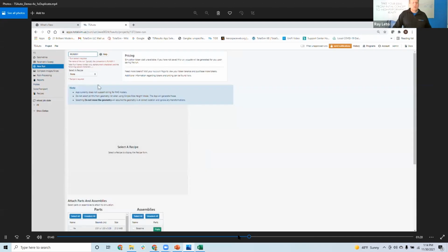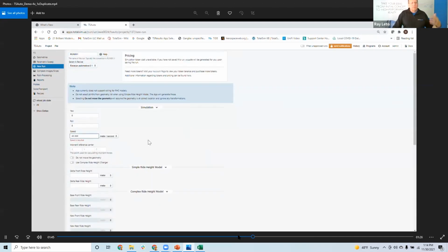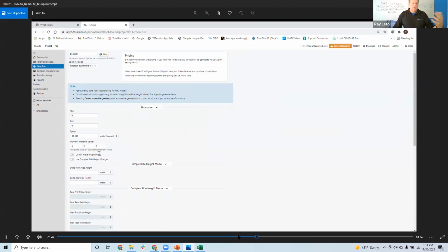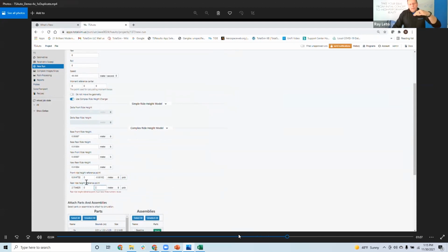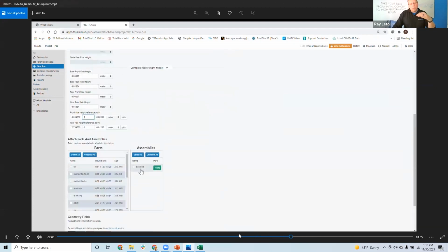And then we can create a run. And from this, we want to set a speed, a yaw angle, all these things that we're talking about that describe the attitude of the vehicle, what ground clearances we have. And for race cars, typically with a formula car, even sports cars, this ground clearance and where we're holding the attitude of the car is critically important to the aerodynamics.